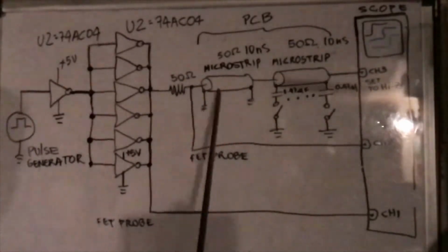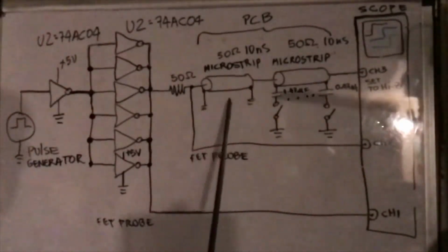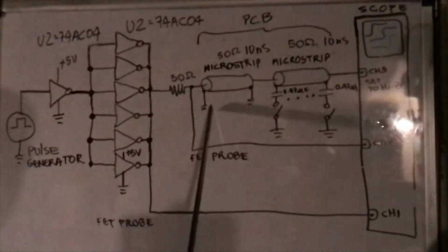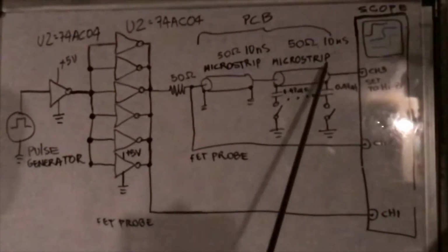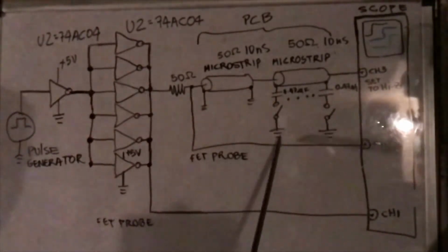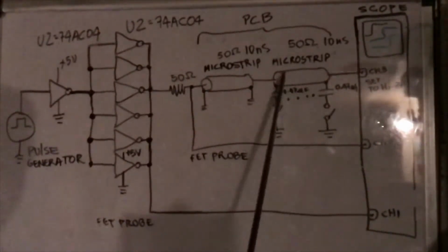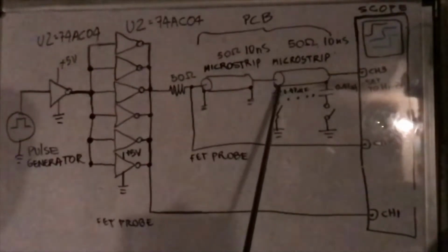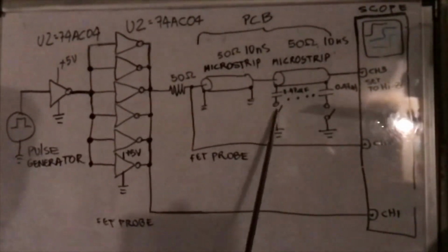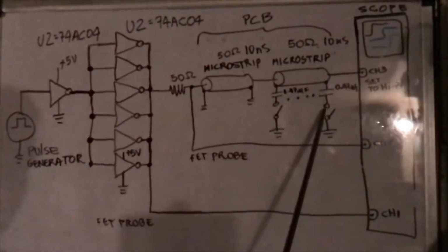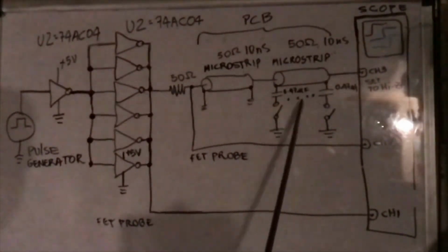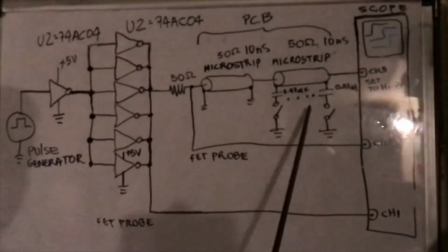The board is divided in two sections: one section has a reference plane connected to ground, and the other has a reference plane that is floating, but that can be connected to ground through capacitors to provide a return path for the high-speed current. These capacitors are located at different spots, as you will see later, to experiment and find the best location to place them.